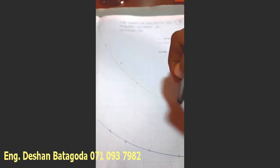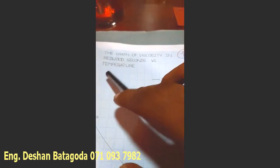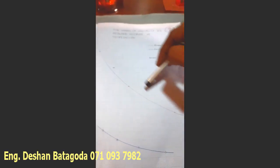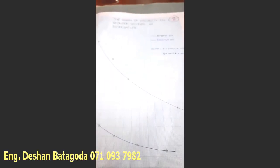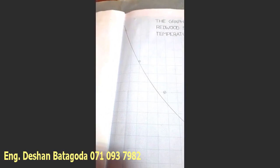Then we are going to plot two graphs on the same graph paper, for engine oil and coconut oil. Because for the engine oil also you know the value for the viscosity in Redwood seconds with the respective temperature, and for the coconut oil also you know that. So now you can very easily plot this graph. One is for coconut oil and the other one is for engine oil. And I will show you a very clear variation.